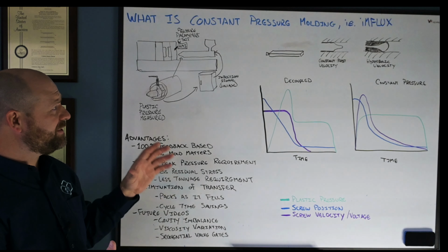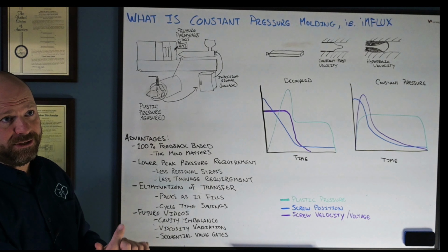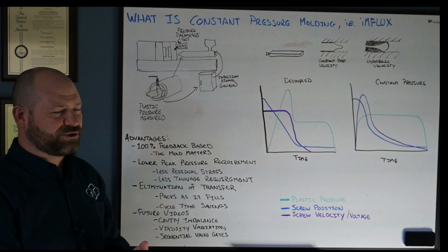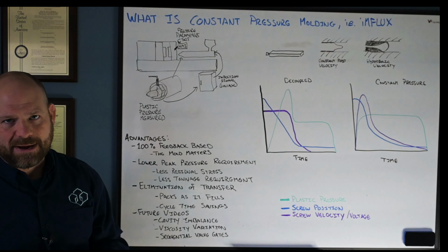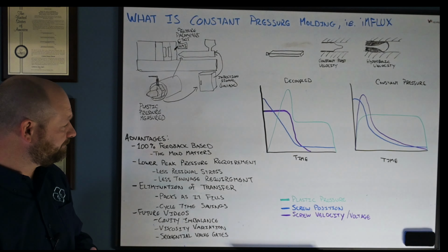So what's happening is the injection profile is being taken over with this technology. Nothing else. Your screw recovery, your clamp, everything else remains the same. Only the injection profile is changed on the machine.